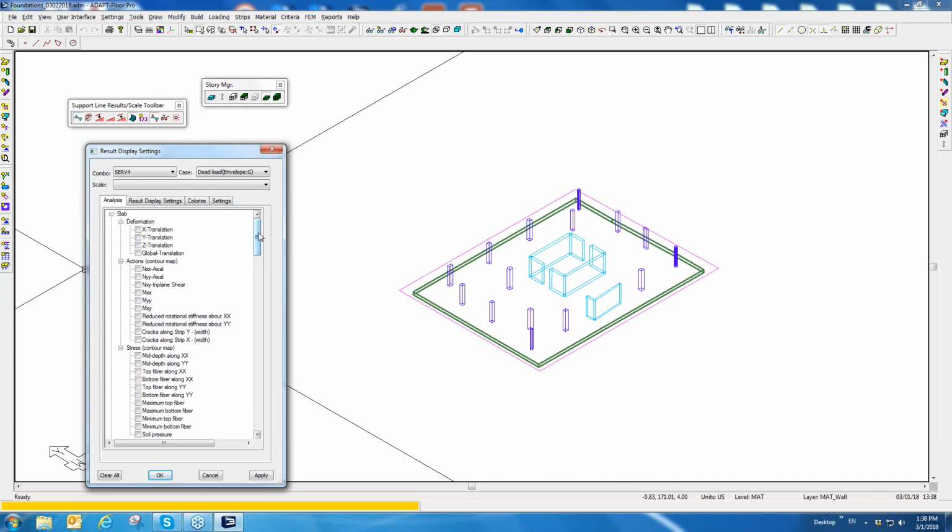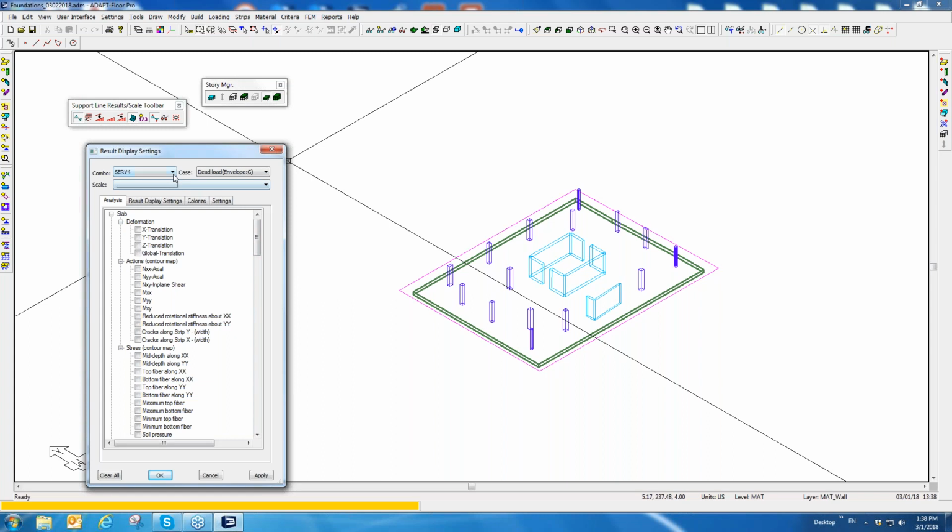So that is workflow number 2, which again is the indirect method where we substitute and then we go back and reapply reactions for the lateral and gravity effects. Okay, so we'll use strength 1 as our, let's say, gravity only comparison. So this is gravity, and then we're going to use service 1 for gravity comparison, and we'll use service 4 for gravity and lateral, because we want to compare this to the direct solution